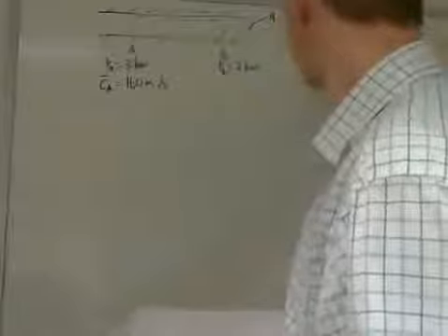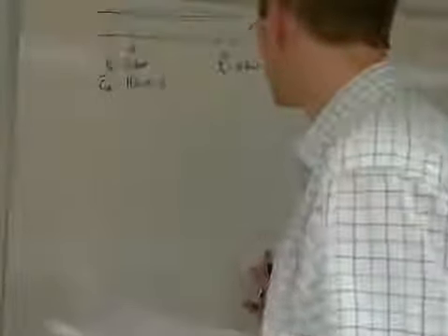Here the pressure PA is equal to 3 bar. That falls to pressure at B equal to 2 bar. The mean velocity at A, so we'll call that C bar, the bar is for average, at A is equal to 160 meters per second. We need to calculate now the velocity at point B. Now the area is constant, 100 square centimeters. However, because the pressure changes, the density is not constant.